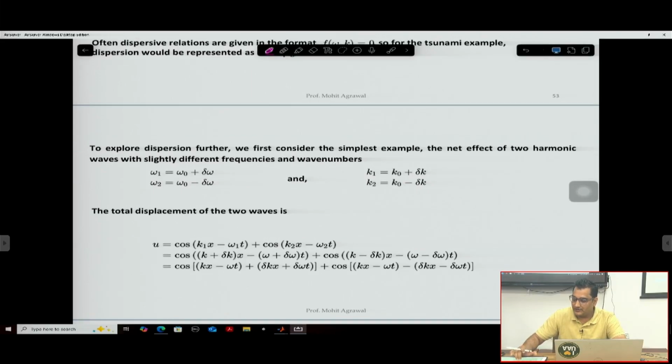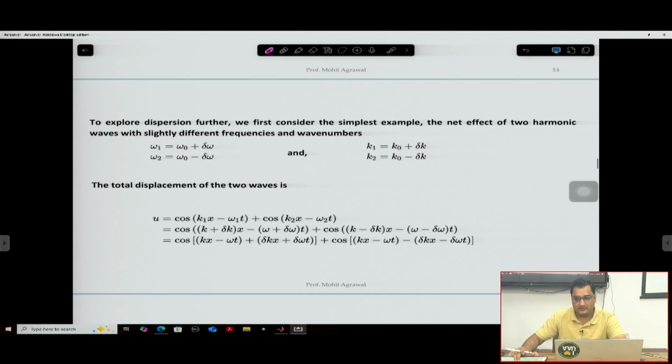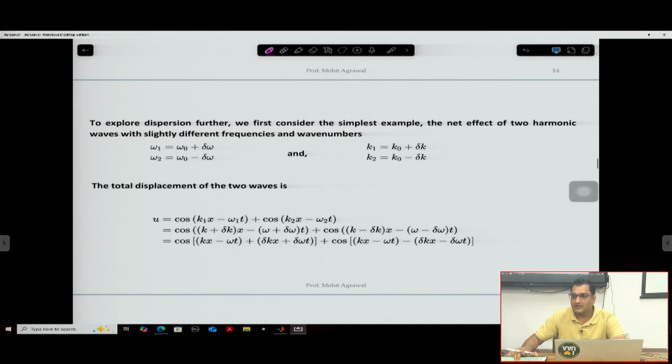And we also said that waves, for example SH waves, when they reach the surface, get trapped over there, and multiple reflection occurs, since the material is anisotropic and heterogeneity is there. So the waves will vary slightly with respect to frequencies and wave number, and they will superimpose with each other and result in the phenomenon of dispersion.